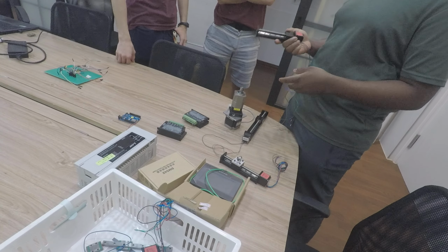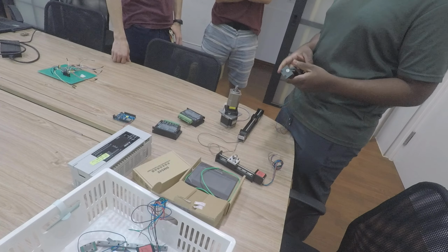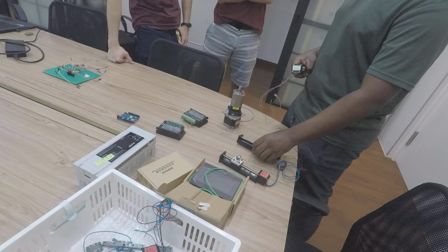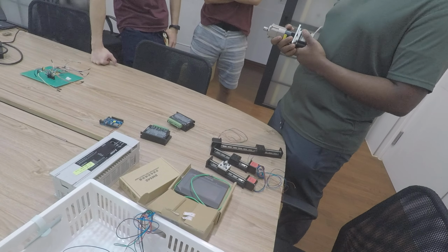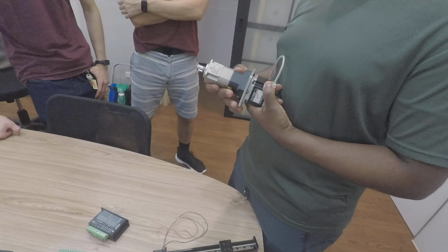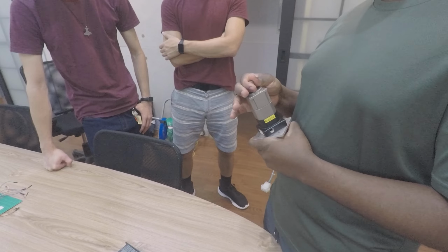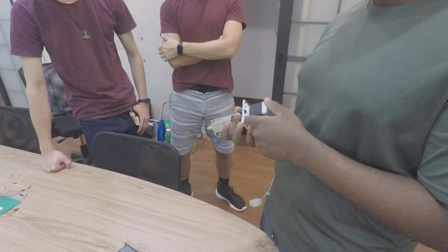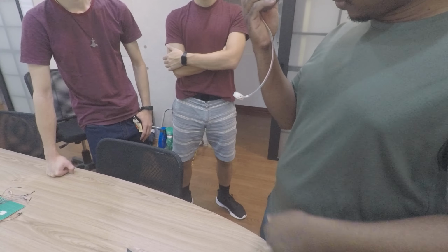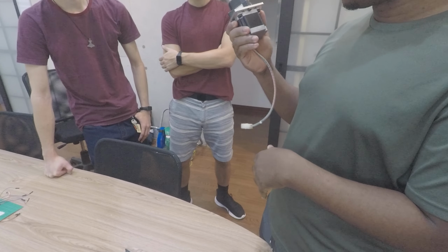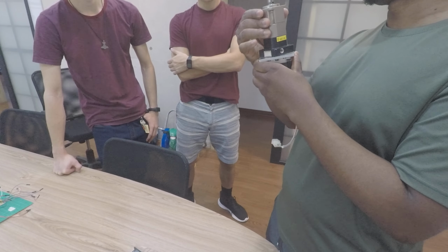But if you want more accurate control, then you need to use closed loop. We have a series of motors, one, two, three, different lengths. This here is a stepper motor, but its big brother. We would say this is a rotary actuator because of the way it acts. If you break this down, there are likely three parts, though probably just two: the stepper motor at the bottom, and then the gearbox.